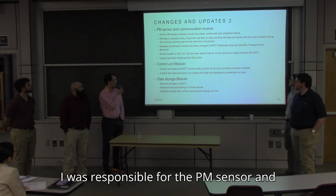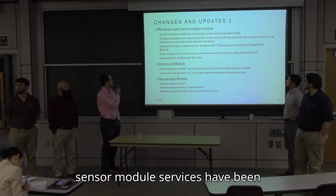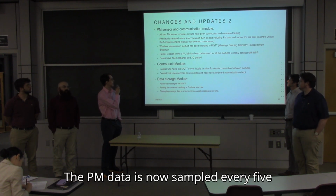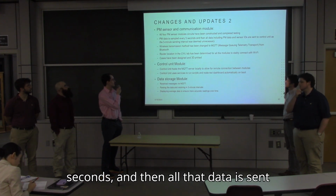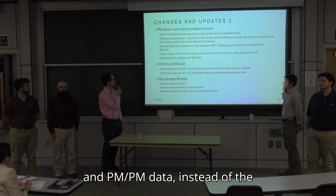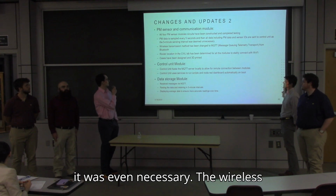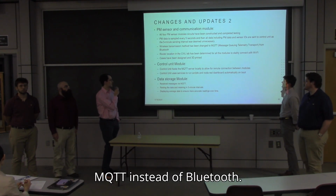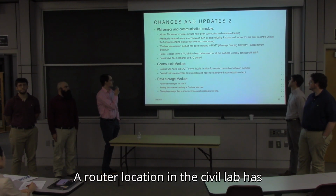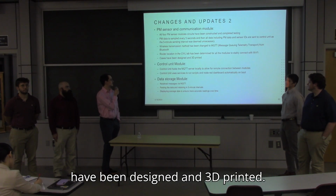I was responsible for the PM sensor and communication module. All 4 PM sensor module circuits have been constructed and completed thorough testing. The PM data is now sampled every 5 seconds, and then all that data is sent to the control unit, including sensor IDs and PM data, instead of the 5-minute standard interval, because it was deemed necessary. The wireless transmission method has been changed to MQTT instead of Bluetooth. A router location in the civil lab has been determined for all modules to connect with Wi-Fi stably, and the cases have been designed and 3D printed.